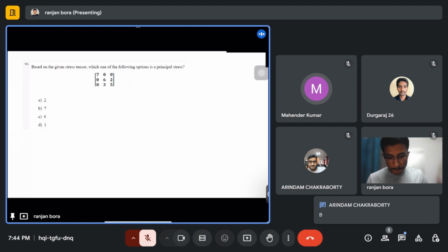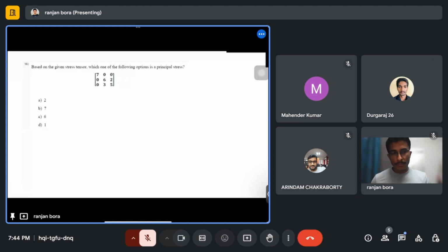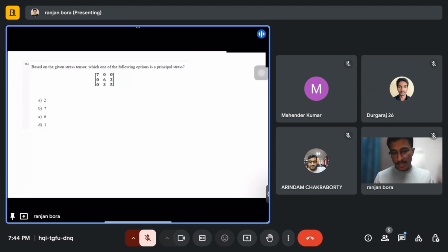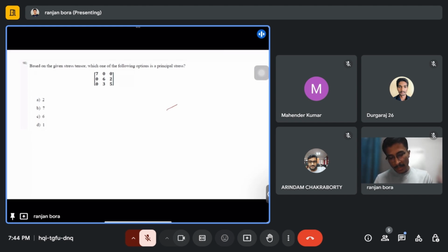See, you know the definition of principal stress, right? Sorry, B is the answer. Yeah, B is the answer. So the definition of principal stress is, if in a plane there is only the normal stress and there is no shear stress in that plane, then this normal stress is known as principal stress.